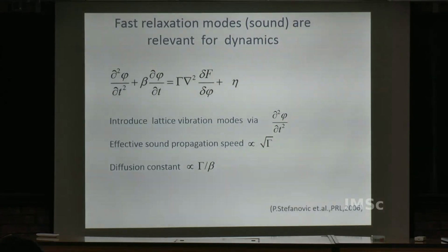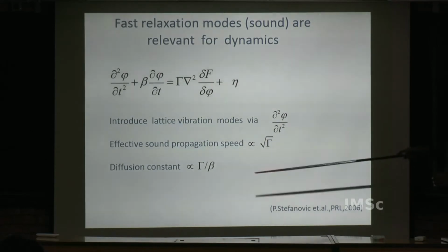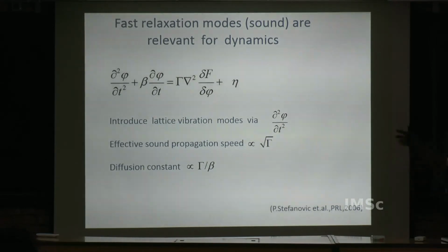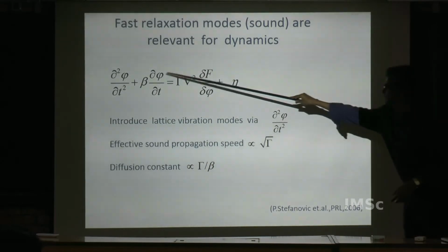Let me defer a little bit why polycrystal, but the model which I showed you was quite good for getting an equilibrium crystal, an equilibrium 2D triangular crystal. Now people found that this model is not very good for studying dynamics. Meaning when you are deforming the system and, let's say, putting a high shear strain rate, then the dynamics is not very well captured if you just keep this part.